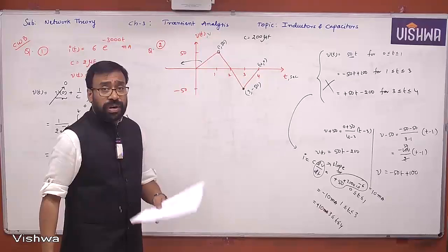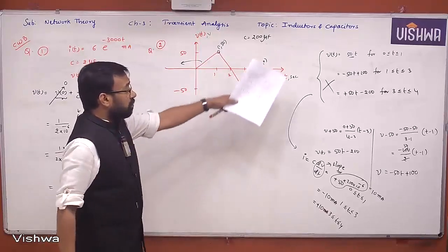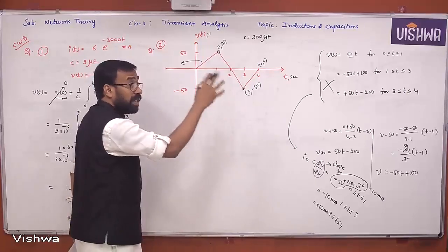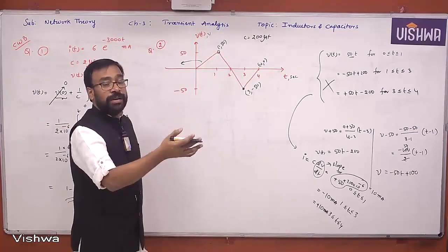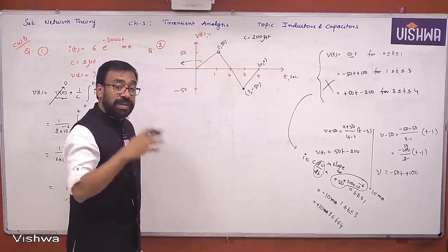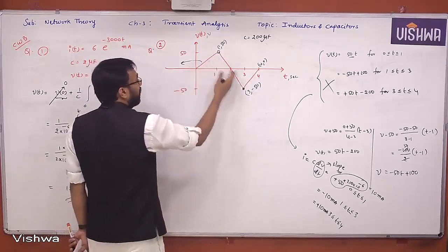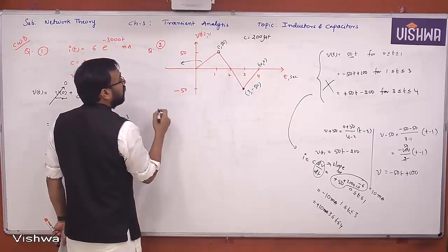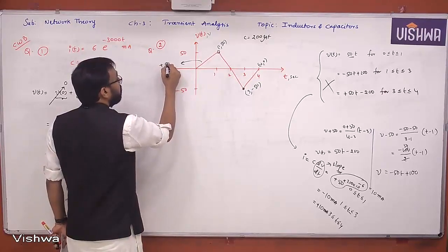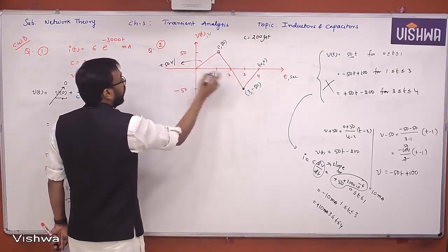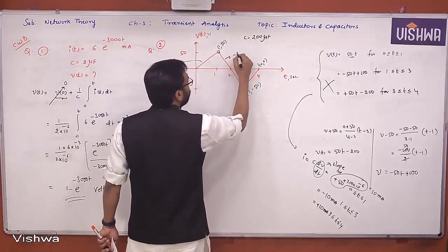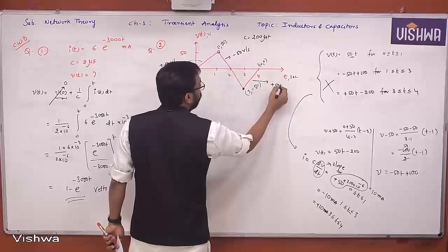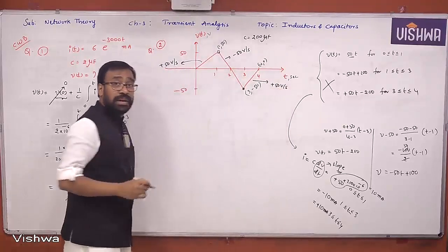Understand all of you? If you are really expert in all this, there is no need to calculate all these things first of all, but I just want to show you that this experience will help you a lot in defining the waveform mathematically. But since they are all straight lines, you can already use the well-defined slope formula. This is plus 50 volts per second. Yes or no? This is minus 50 volts per second. This is plus 50 volts per second. Understand all of you?